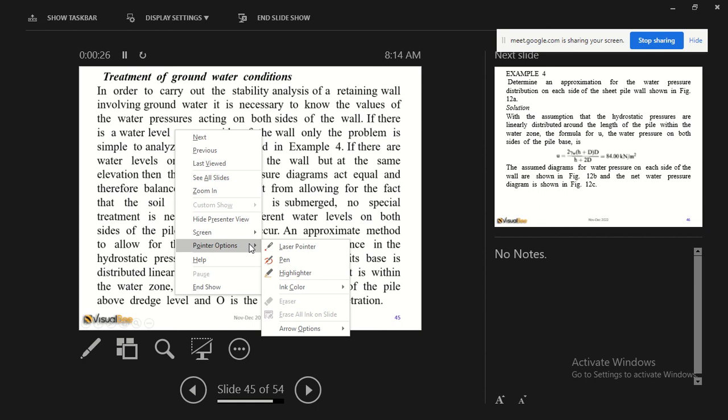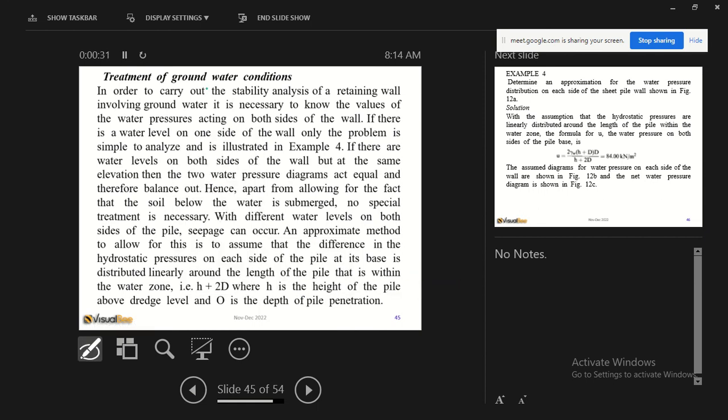So we took the most simple case that we have the same water on the same side. However, if we have water on different sides and different elevations, of course water would tend to seep. The one with higher level, water would tend to seep to the other side. There is a higher head here, so water would flow to the other side.